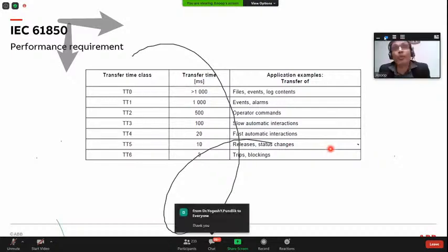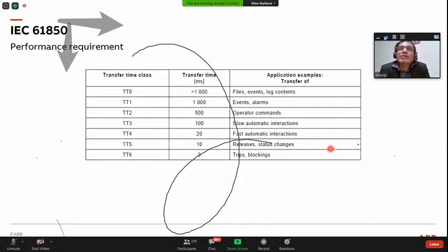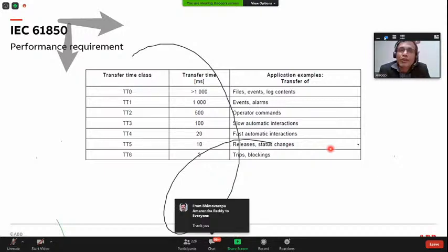Look at my first slide where I was explaining the fault, where one device is saying there is a fault and telling the other device not to operate, and I am sending data to the device in real time. Real time is not literally possible because you have intrinsic delays, so it should reach the device in at least 3 millisecond or 10 millisecond. So we use Goose for this transmission. Goose is mainly used for all the time critical information.